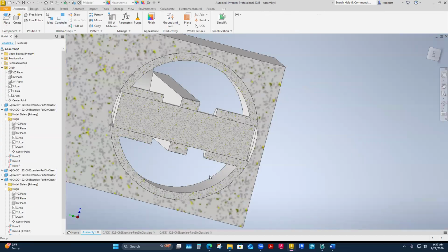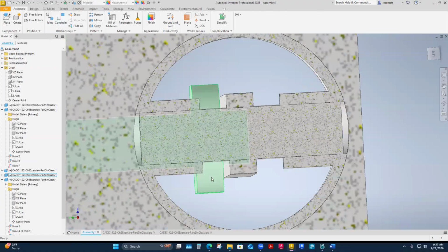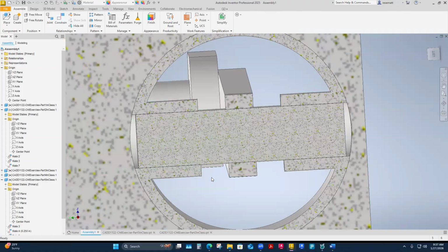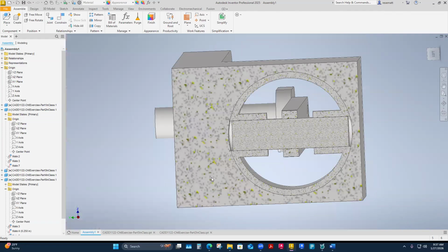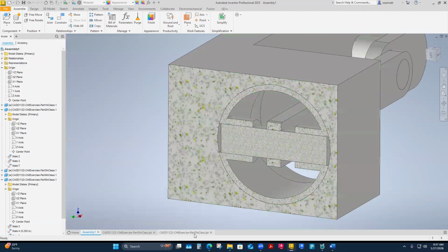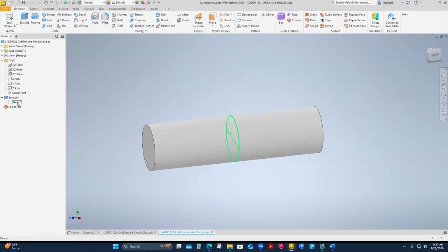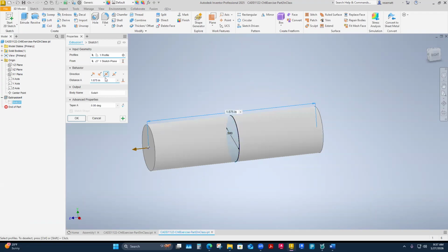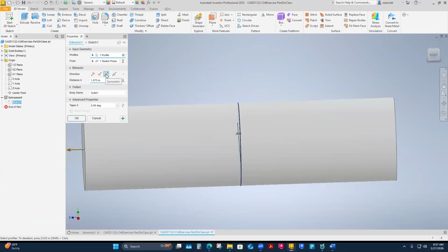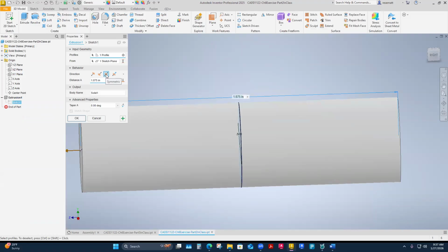And I'm going to check my alignment. I don't have an alignment issue now. So that would be how I would prefer to do that and not use some weird dimension. I always want their center lines to be constrained together. Well, what I fixed was how I extruded here. However you've extruded this part, I chose to extrude centered over the plane, symmetric from my sketch. I'm symmetric to each side of my sketch rather than pushed to one side or the other. I'm centered, which really is this.